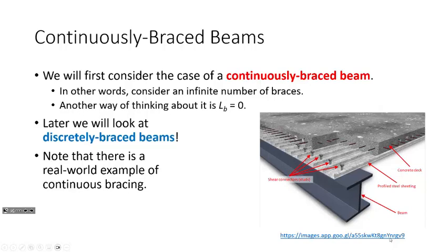We have a stud welder, we take the stud, we load it into the stud gun, and it shoots the weld right through the pan, right into the top flange. We have a series of those studs along the top flange, and then we get out our concrete truck and we place the concrete, and that concrete cures and locks with those shear studs. How many of you have ever been on a DOH construction site and seen the concrete deck placed and seen these shear studs I'm talking about?